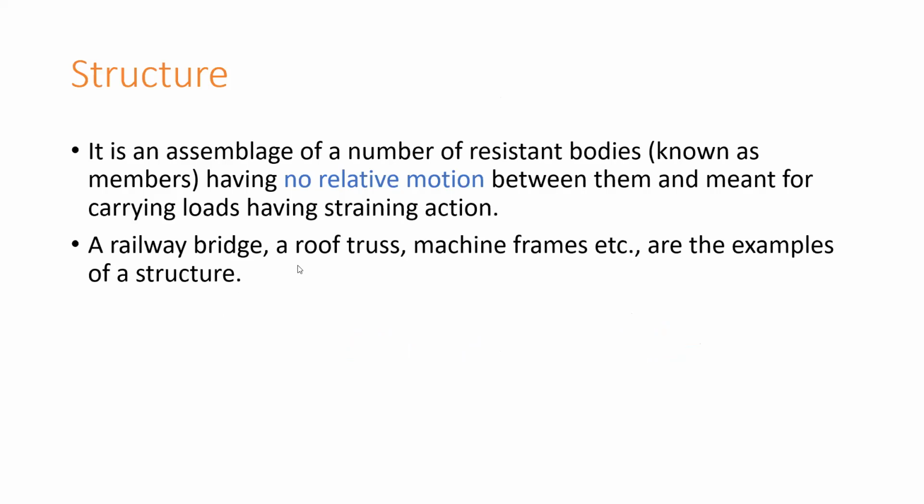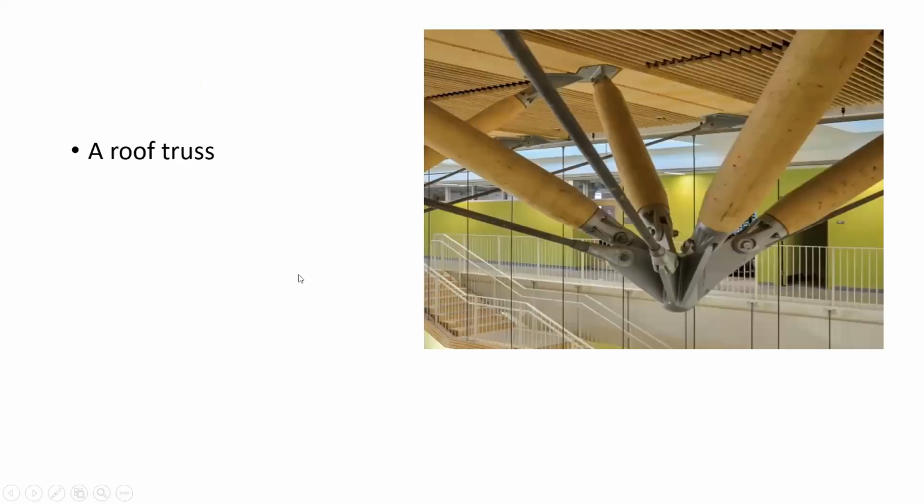No, sir. Okay, so see, it is an example of a structure, a roof truss. Like this, all these are the members of the structure, but there will not be any movement between these two members or between any two members. No movement will take place, and this structure will carry the load on it. The load may be compressive, the load may be tensile.